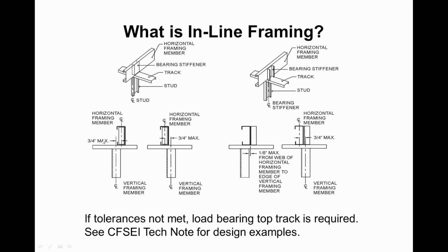The track section would then have to transfer the load if the joist is sitting over here, for example. The track section has to transfer the load from this location over to my stud. Well, we all know that these track sections are not very strong, especially as you load them in this direction as oriented. Therefore, what we want to make sure is that this joist member is close enough to this stud such that I get, again, this direct load path for this load that I've got here to transfer through this connection. So how close is close enough?